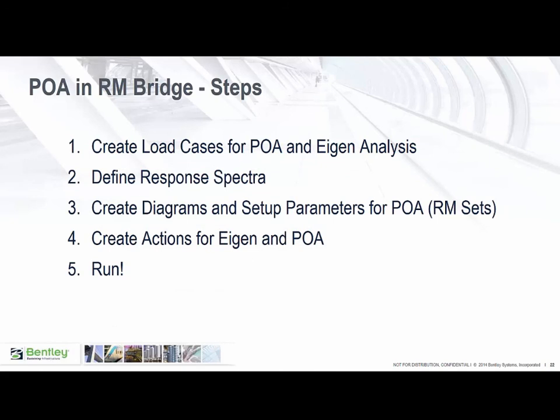First, we create load cases for pushover analysis and eigen analysis. Then we define our response spectra. After that, we create our diagrams and set up the parameters in RM sets. Then we create actions for eigen and pushover analysis, and then we run the model.